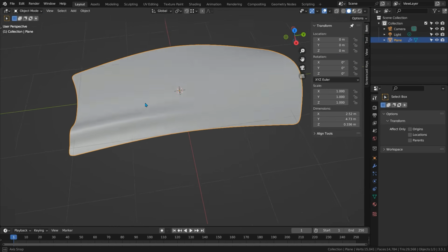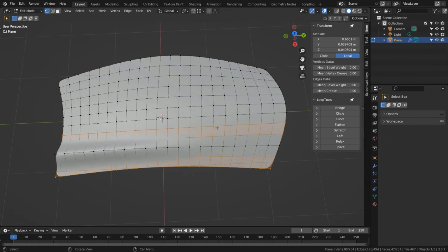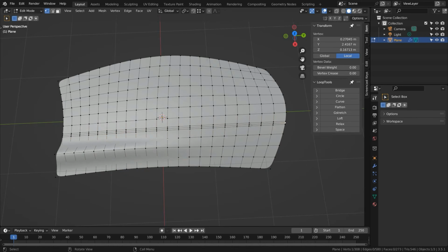Okay, that looks fine. Now I might want a much sharper detail, and again, if you look at modern cars, you'll see this everywhere, on almost every car. I'll select a loop here and press Ctrl and B to bevel it. I'm going to roll my mouse so that there are 3 loops. I'm going to move it to around here, and I'll do the same kind of thing again.